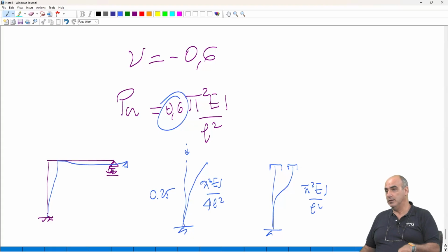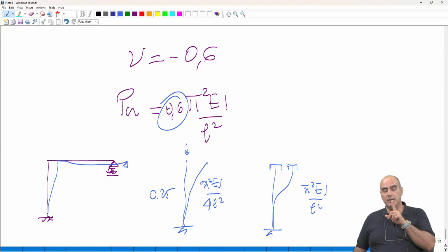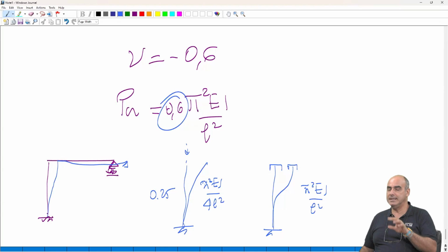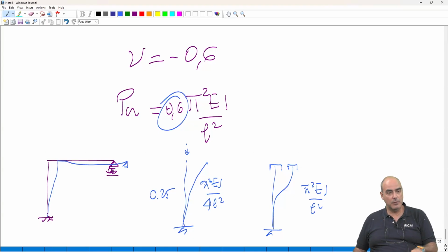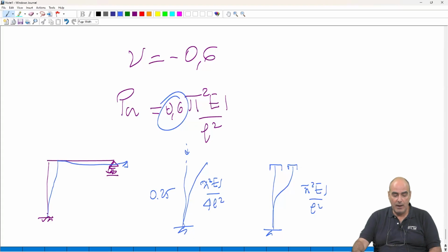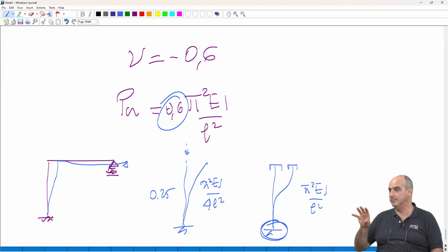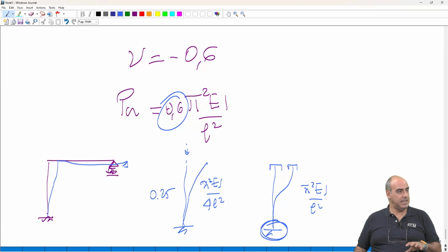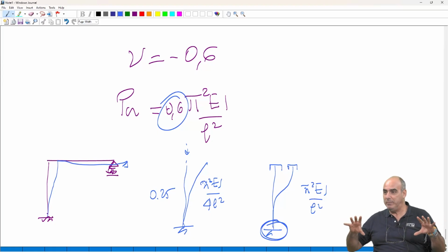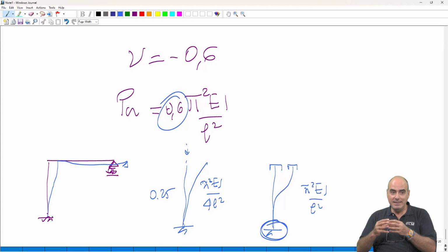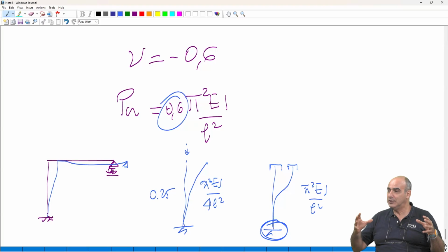And also, I am just anticipating some concepts that we will see tomorrow. The connection in our drawing here, this is a beam foundation, a column foundation connection, is a point. The connection is a region of the structure, which consists of two parts of the elements to be connected and all the devices which connect them. You have to design the three of them.